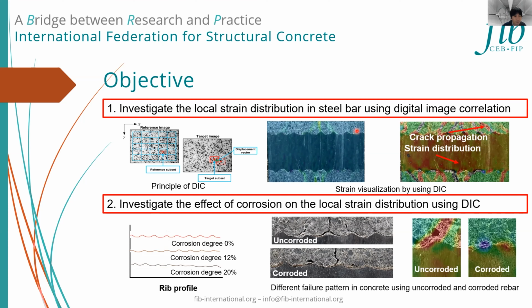For example, the macroscopic total strain of rebars from the applied load, and if you integrate the strain distributions along this line, the data from the DIC, can you say the data are almost the same? Maybe comparing macroscopic strain and the calculated total strain from the DIC data. That's what I meant. Oh, I see.